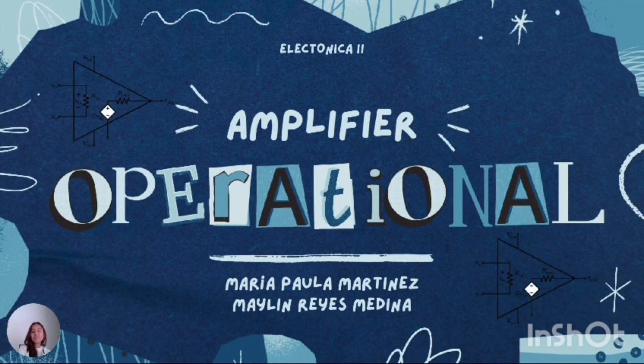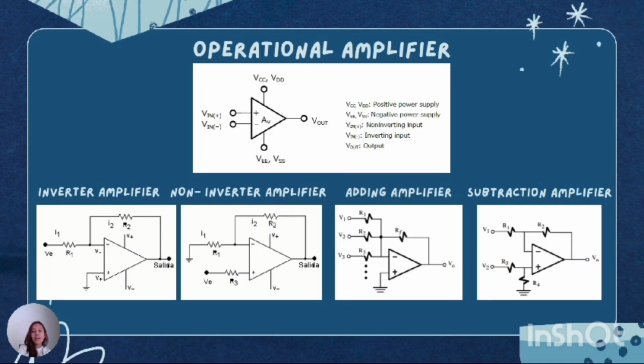My partner is Reyes, and we will talk about operational amplifiers. An operational amplifier is an electronic device used to amplify electrical signals. It is one of the fundamental building blocks in the design of analog electronic circuits. The typical operational amplifier has two inputs, one inverting input and one non-inverting input, and one output. The output is the difference of the inputs multiplied by a gain factor.